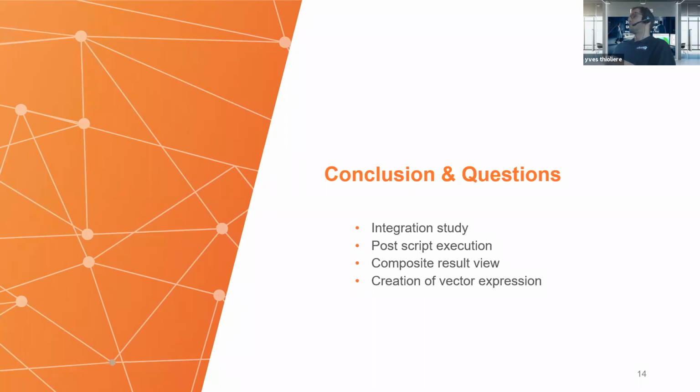So indeed, in the calculation of the FEA model, the voltage limit is not taken into account. It's afterwards, in the post-calculation, when you create the efficiency map, that you specify the DC voltage limit, and then the algorithm searches for the points that fit that voltage limit. Also, you can check the tutorial for creating this efficiency map.